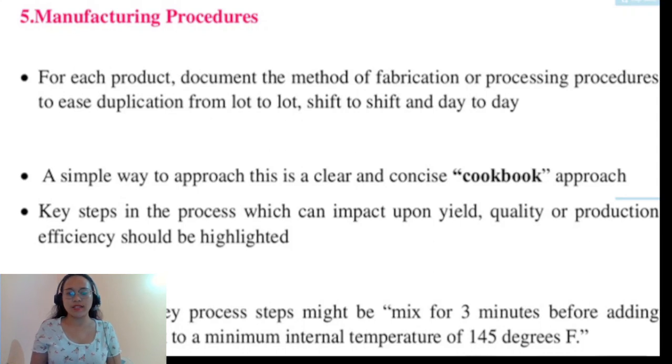For each product, document the method of fabrication or processing procedures to ease duplication from lot to lot, shift to shift, and day to day. A simple way to approach this is a clear and concise cookbook approach. Key steps in the process which can impact upon yield, quality, or production efficiency should be highlighted.